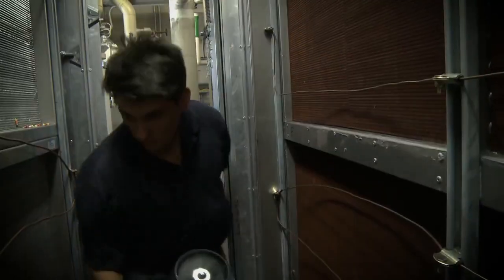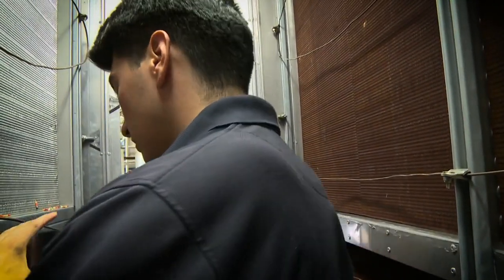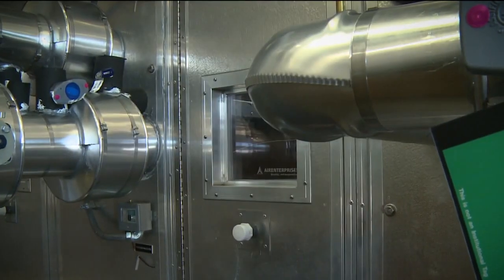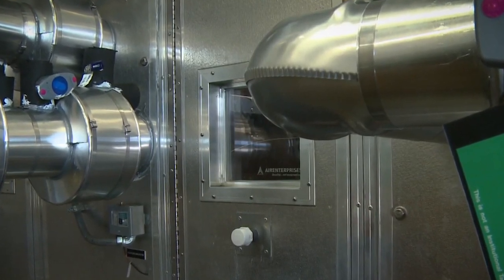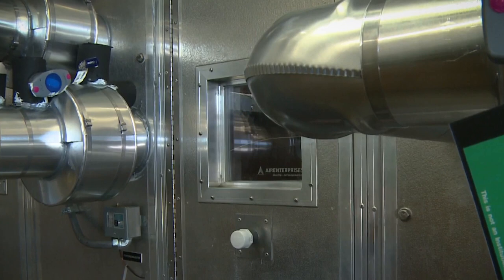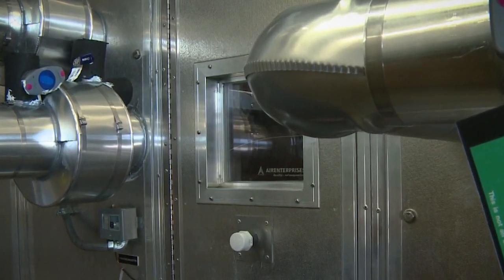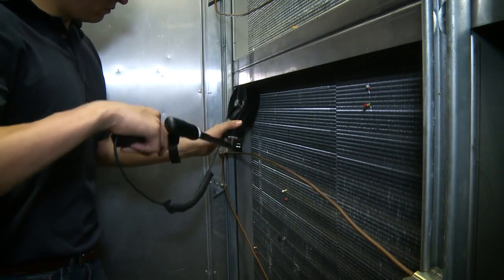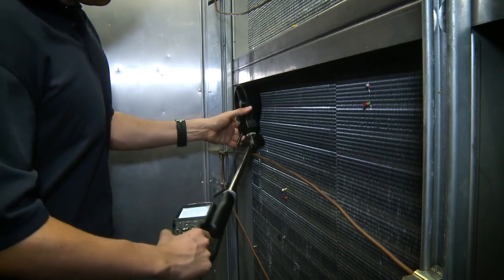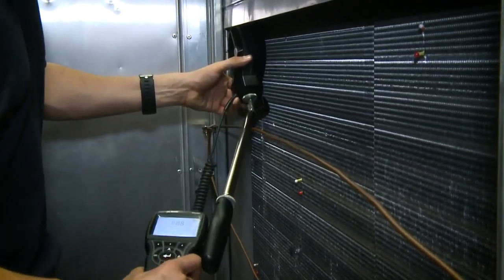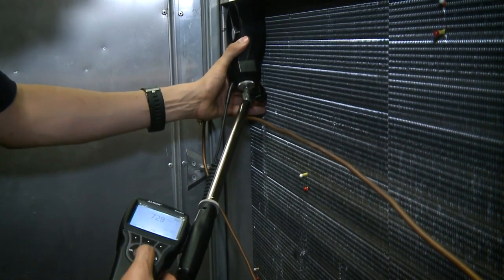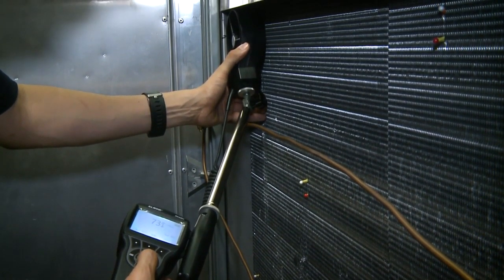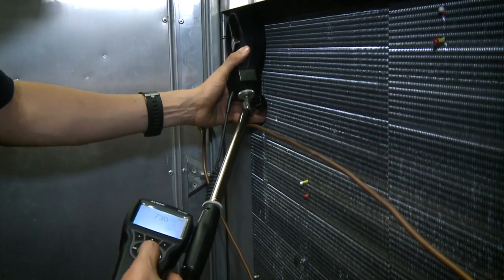Due to the small and narrow size of the preheat coil's plenum, they were measured and marked for the standard and offset velocity reading locations prior to this video, using the same method shown on the demonstration coil. When conducting the readings, place the vane anemometer's head parallel and flat against the coil with no obstructions so that the airflow is perpendicular, and the vane anemometer can record an accurate airflow reading in feet per minute.